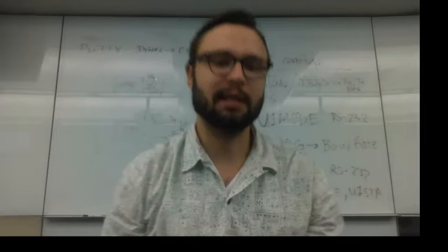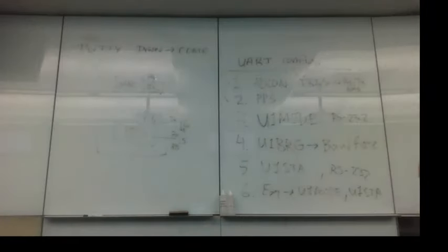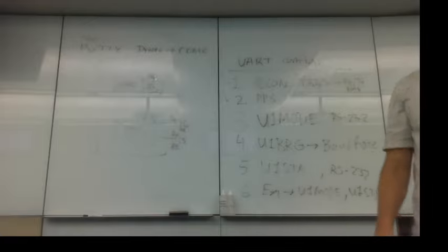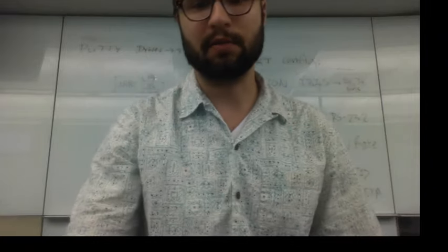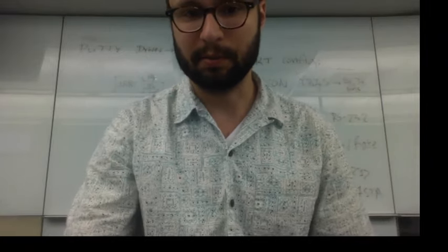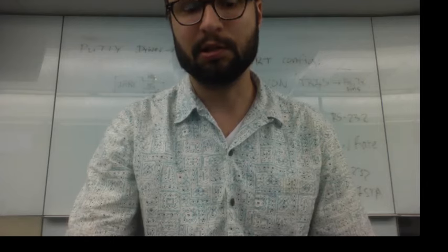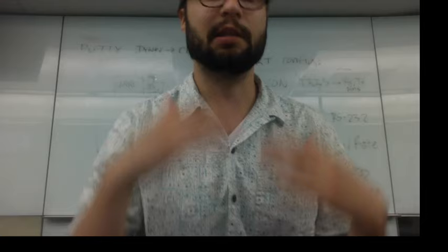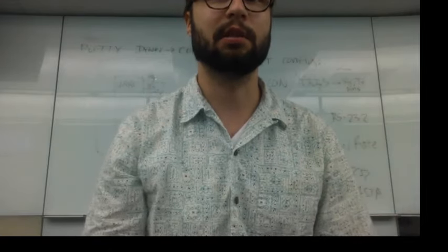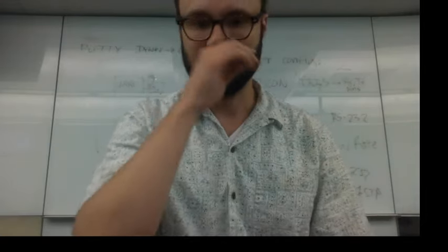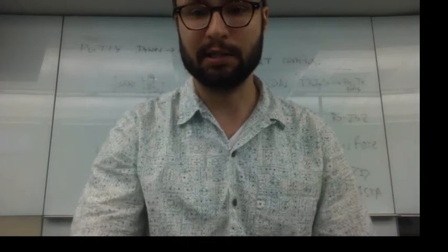So if you want to save the 4 primary working registers, you can do this before an interrupt service routine, and it'll save all of them in one instruction cycle. But what happens if you don't know an interrupt service routine is coming, which you probably won't? What you can do is you can do this before, like the first line of your interrupt service routine. So let's see if the compiler actually does that.